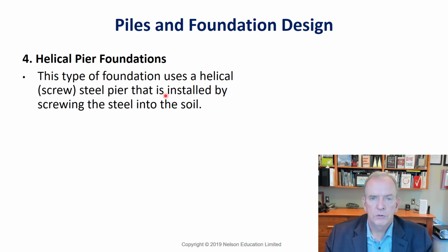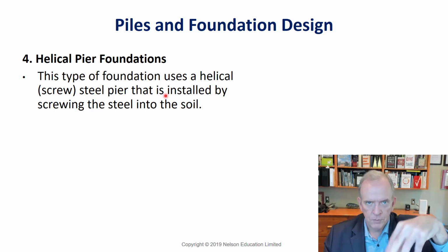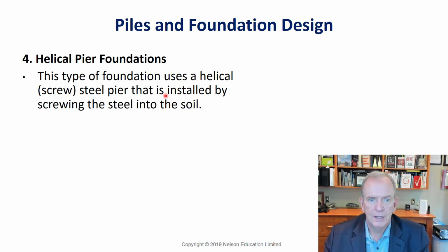So helical piles, those are also used a lot. They're actually drilled in, and it's calculated how much. They look like a drill bit basically. And they're calculated to support the loads above. They can be installed pretty readily, and can be used for remedial work, a building that's settling. They can be used in new construction as well.